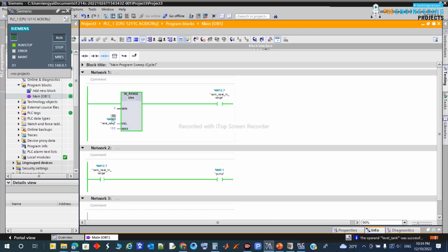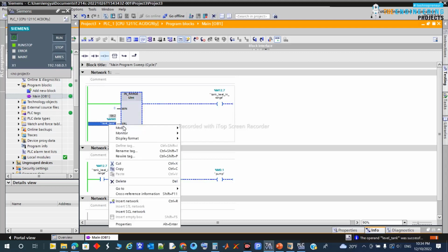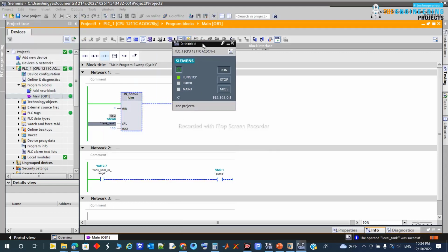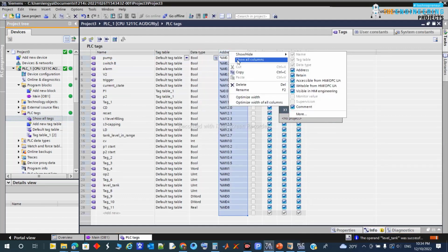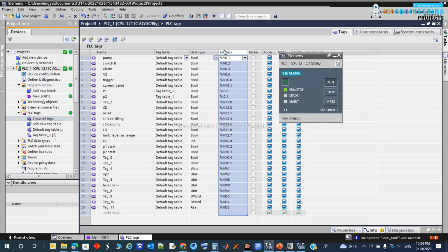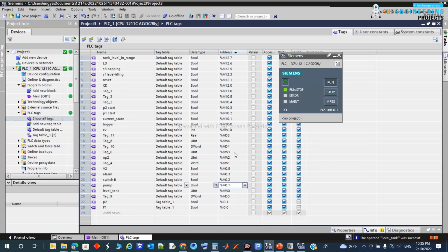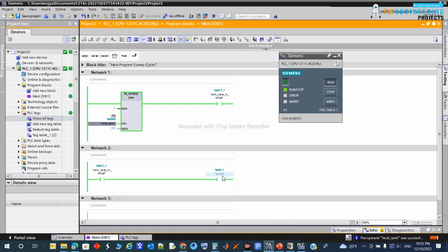I think this is connected with some data type. Let's look at all the data types we have here. It's good to know the PLC tags here. If we order the tags by address, and CMW, I got to know now, because you're using many like M05, M03, all these overlapping with MW0. That's why when this one becomes true, M01 will be true, changing the value of MW0. So that's very good to know,